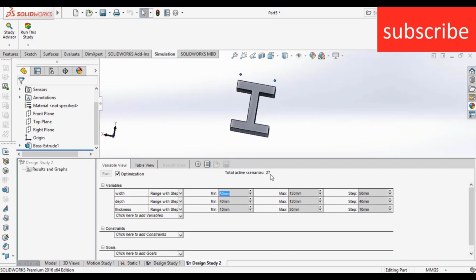Here you see it will run a total of 27 active scenarios, but as you know my total width is 100 mm, so I want my minimum width to remain 100 mm and depth to be at least 80 mm, so that the scenario isn't affected, and thickness 10 and 30 mm. Now a question arises in your mind, why am I selecting the step value of 50 mm? Maybe some people don't understand what depth 50 mm, 40 mm, 10 mm means. Don't worry, when I run this simulation you will realize what it means.